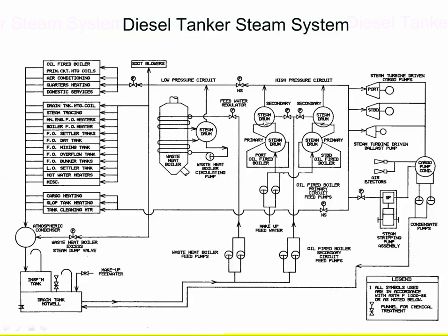So what's going on is I want the efficiency of a 1,200-pound boiler, and I could go to the additional expense of putting in these steam-to-steam generators so I could run these 1,200-pound boilers. I don't have to worry about deoxygenated feed water because this is a closed system, and it was initially charged with hydrazine. Nothing should change, and my chemistry shouldn't change.